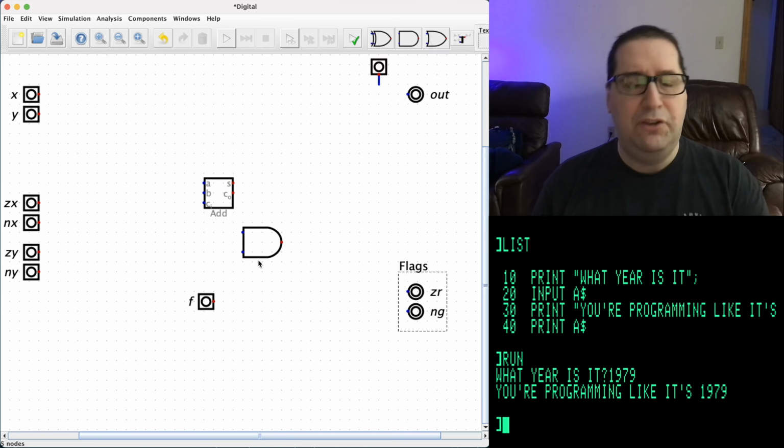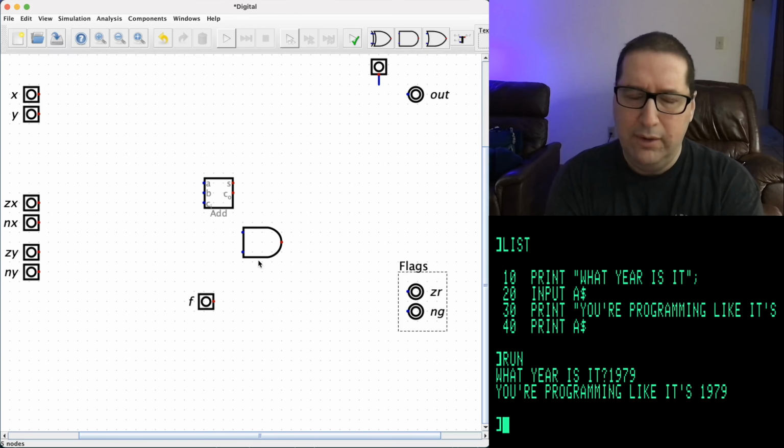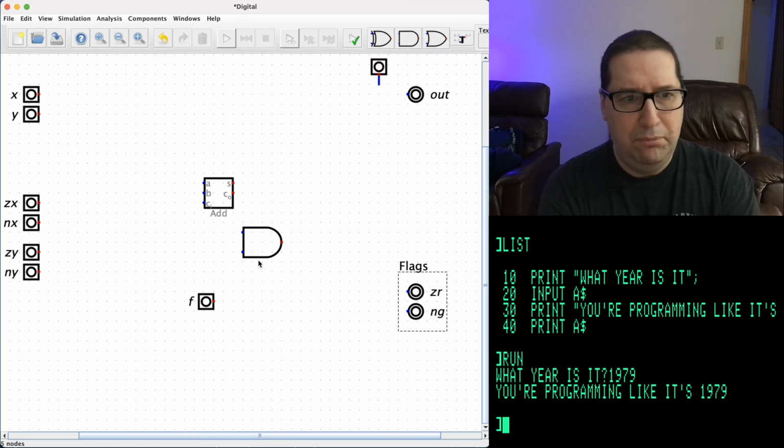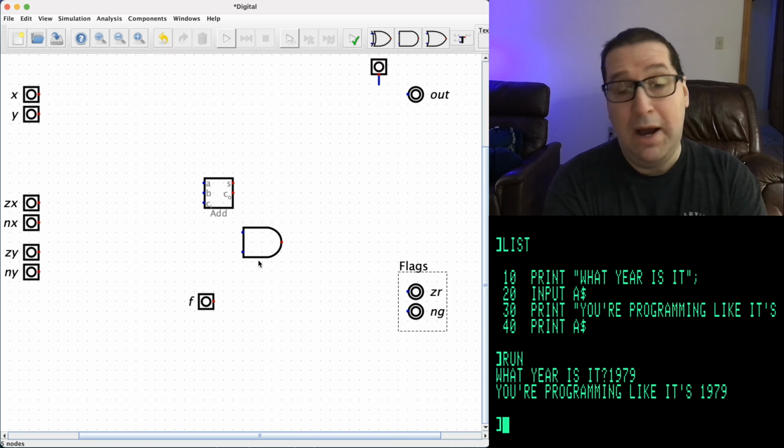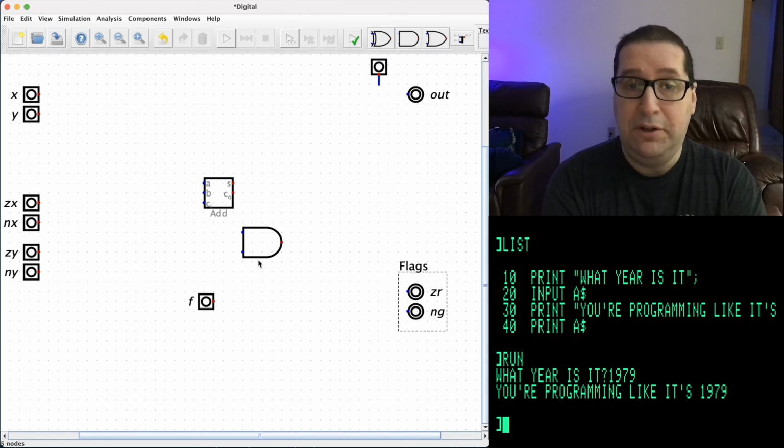So which of those makes sense in this scenario? Well, we have two inputs here, and using a demux, which would take multiple inputs and send them to a given output, actually gets tricky if you have multiple values you're juggling here. So I think the thing I want to do is, since I'm not concerned about any kind of efficiency, I want to always be computing both X and Y and X plus Y, and then I'm going to use this F flag to select between the results.